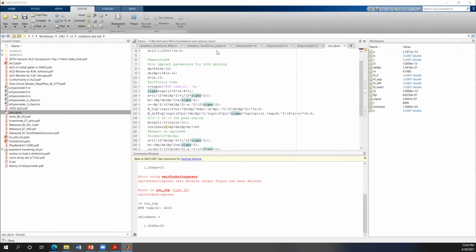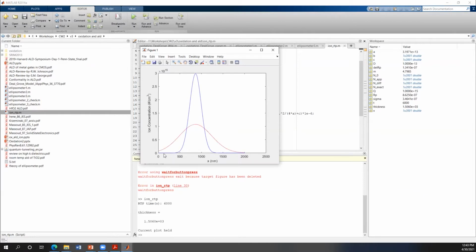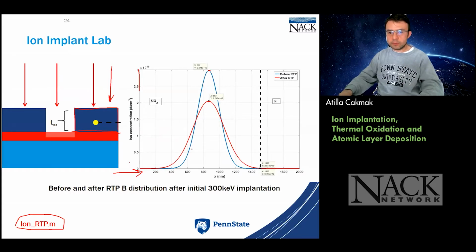Okay, so this is the same thing right after the ion implantation. Look at the distribution, 3 times 10 to the 15 per centimeter cube. That's the concentration of the ions in here. And this is what's going on after leaving it in there for, what did we say, 100 minutes. That's crazy. This is a very long time, and that looks like the tail. The tail says I really infiltrated a lot into the depths of the material. So that's not great news for you, because your mask does not serve your purpose anymore. Your mask here will not stop the material, so it will infiltrate into silicon.